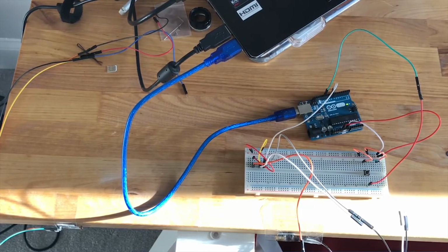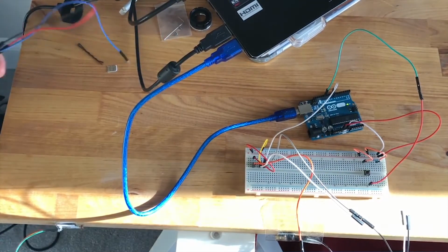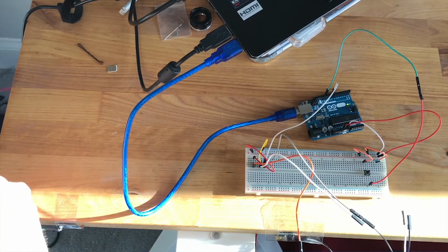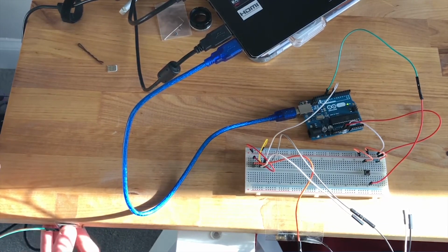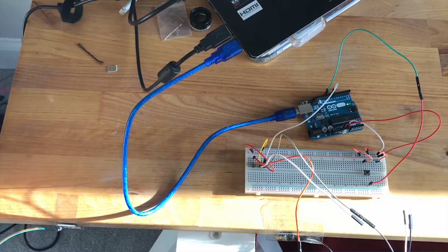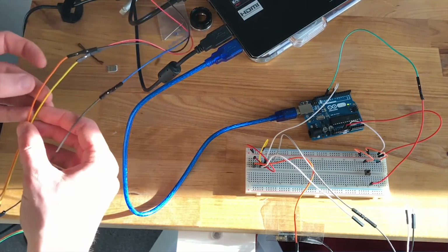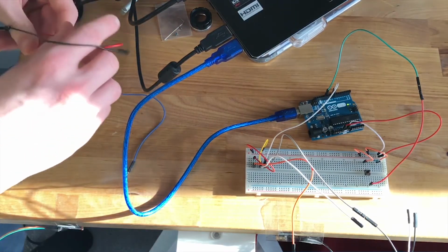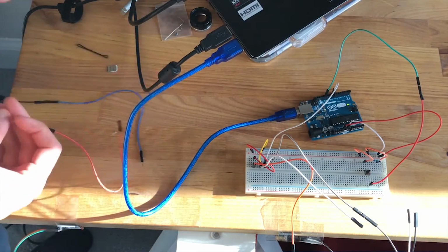and it will work. The only main difference is that the signal for this one, we are going to plug into an analog read because we want a streaming value. So here I have green as my signal, yellow as my power, and then orange is going to be my ground. So I have signal, power, ground. And again, this is a prime example of why having good, correct colors is important.